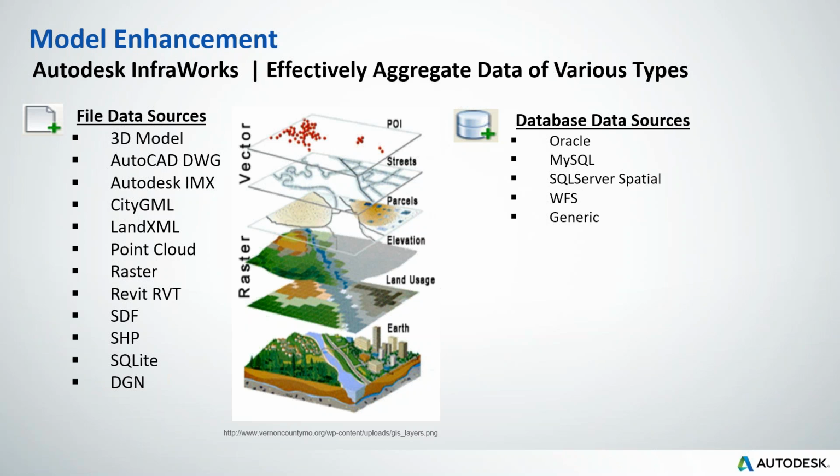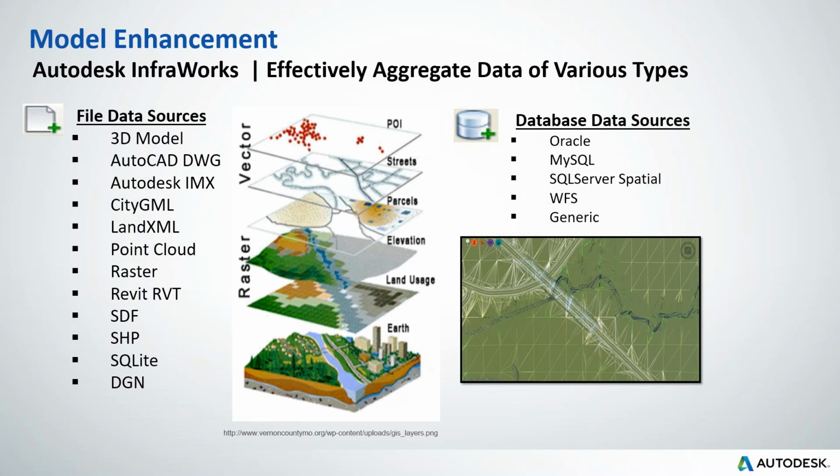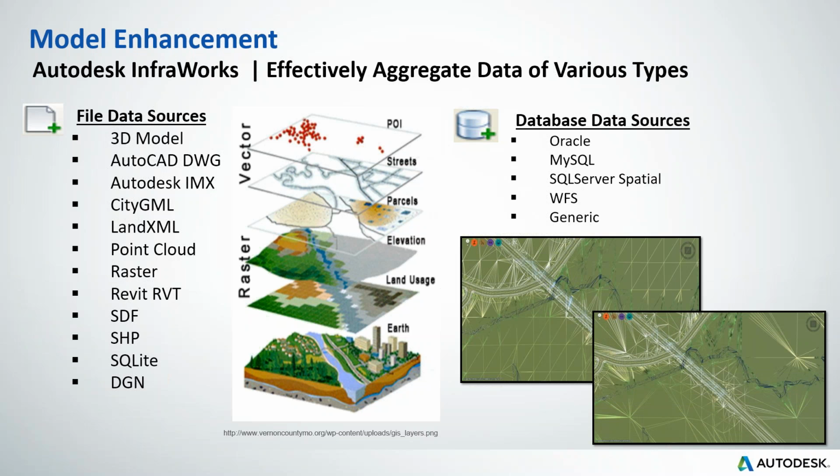Just to give you an example of how things work in Infraworks. So basically, the terrain that we're going to get from Model Builder is not 100% accurate. And this is mostly the case, right? So this is what we will see inside of Model Builder. A little bit of triangulation here and there, but basically not much. What we are supposed to do is bring in the point cloud data, extract the surface from it, or else if we have a surface that's residing in Civil 3D, maybe generated in Civil from surveying points, then we can bring that data in and then update or upgrade the existing surface with the most accurate surface that we have from surveying. Then we can kickstart the design process inside of Infraworks.